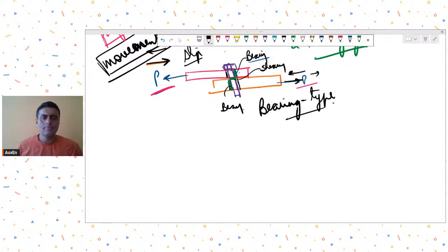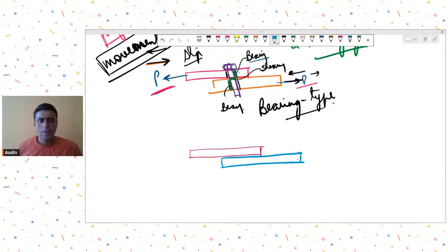So now if that has to be avoided, for such connections where you cannot have such slippages, instead of having a bearing type of connection, you try to add certain pre-tension in the bolt. Adding pre-tension means that instead of the bolt transferring load through bearing, I apply certain pre-tension in the bolt. When I do that, these two plates are pushed towards each other, correct?